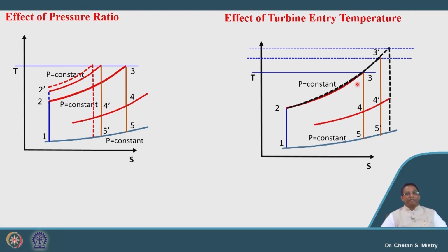Here in this case, if we look at, this is representing the higher temperature or beyond, where my thrust will be improving. But at the same time, since this line is a diverging line, the amount of heat supply required will be increasing, and that will be reflected in terms of higher thrust specific fuel consumption. So, do not get confused or mixed up with what we are discussing at this moment. Just try to understand this part.